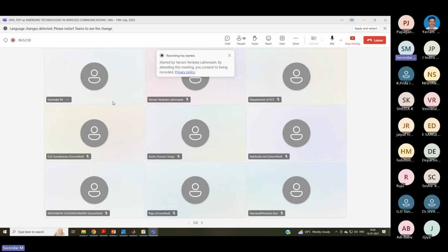Overall, the energy efficiency will be better for RSMA, because the computational complexity involved in doing the SIC would be much greater for multi-layer NOMA, that is, NOMA with more users. But here only one layer of SIC is there. Every user does that. So definitely RSMA has an edge in energy efficiency when compared to NOMA.